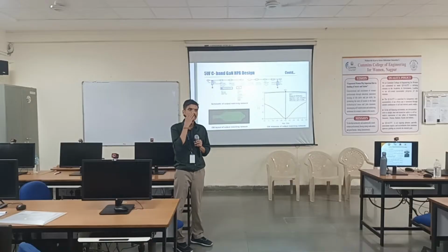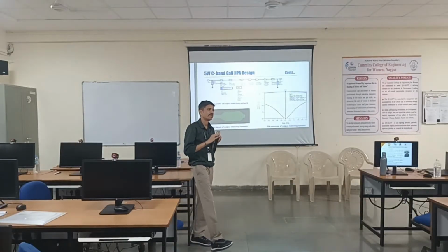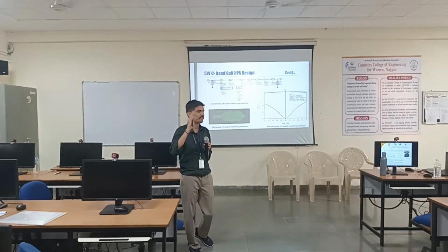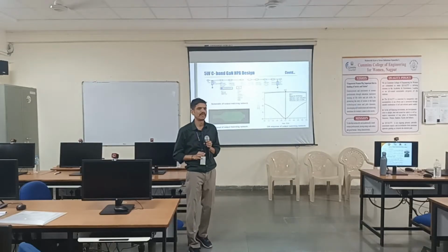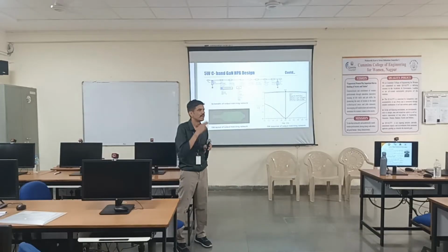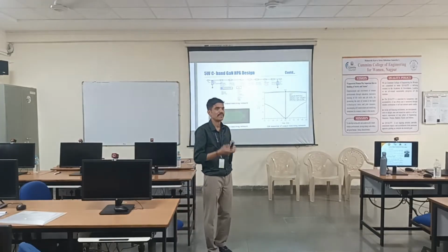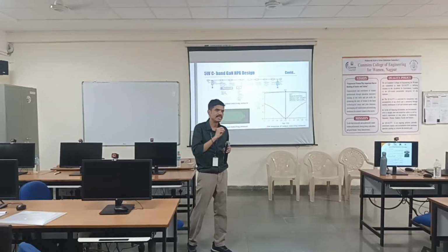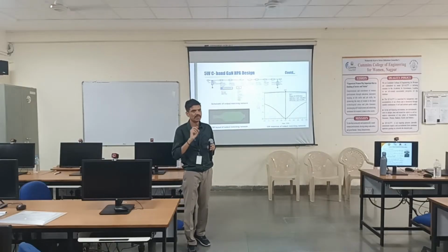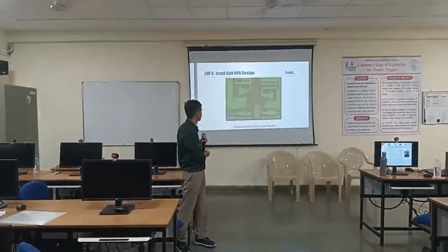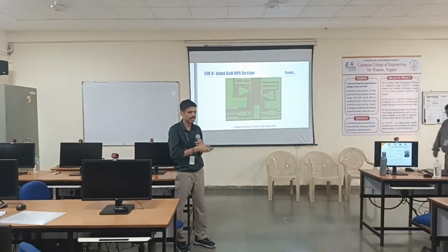So one takeaway: designing power amplifier or any microwave circuit will be easy till 3, 4, 5 gigahertz. The moment you move ahead of that, your life will become complicated. Why? Answer is lambda. Higher the frequency, lambda will be smaller. Smaller lambda means any small changes in your microstrip transmission line length or width are going to affect the impedance matching. This is the picture of the C-band PA.